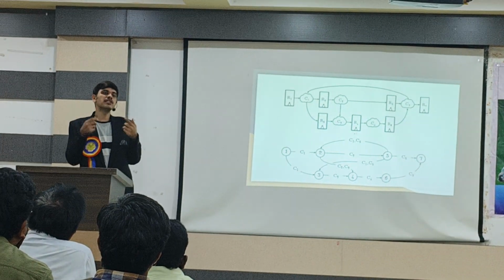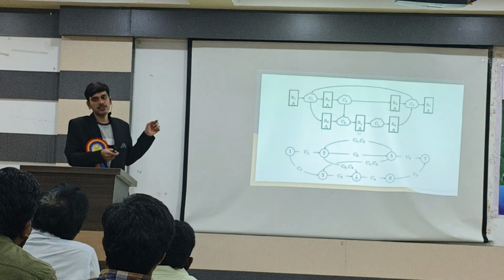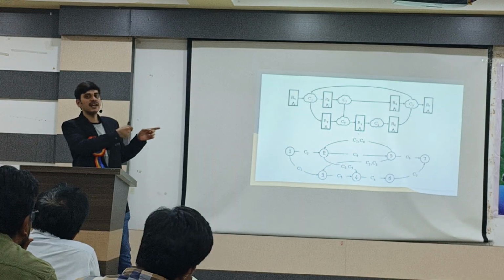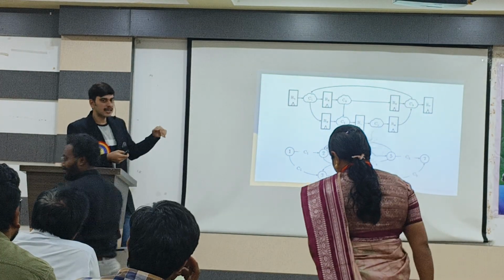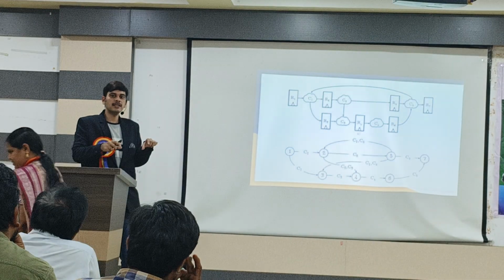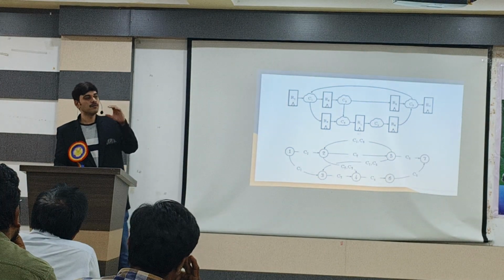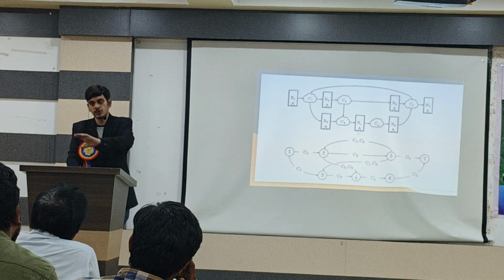So how do we calculate the worst case scenario? You should have the information of every node. Based on the node, where the connections are and what the delay is, all these calculations are based on that only. Which path has the worst timing path, you get to decide it, and we analyze the timing path and we close it.